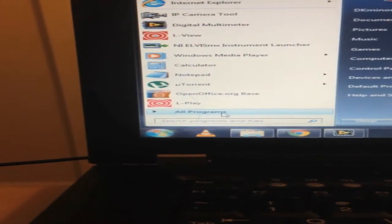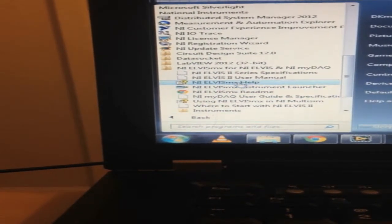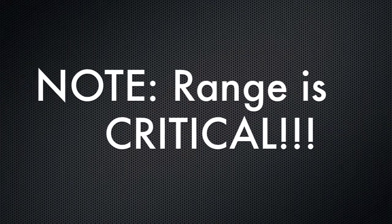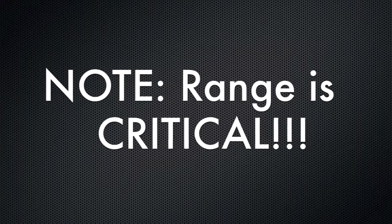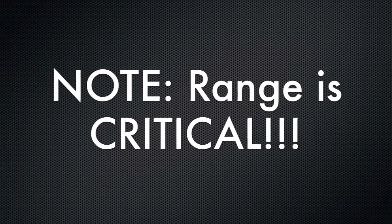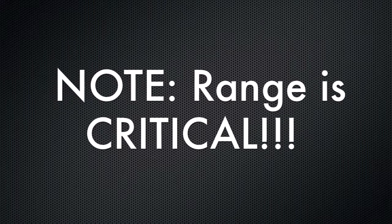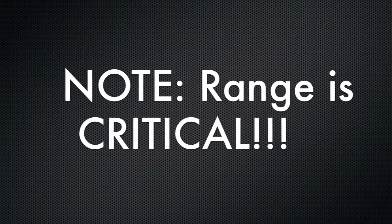To get the LabView digital multimeter running, go into your Start button, find the National Instruments folder, and find the Elvis MX folder. Launch the Elvis MX and select DMM on that box. Probably the most important thing when using the DMM in LabView is to make sure you have the correct range. For example, if you're measuring resistance on the scale of about 1,000 to 2,000 ohms, don't pick 20 mega ohms as your range. You will not get a valid value when measuring it.